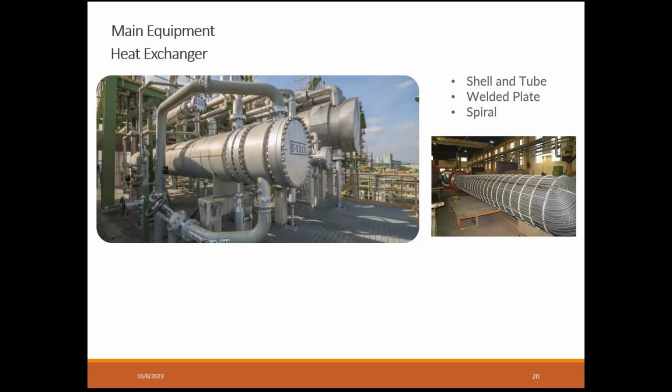So this extra heat is not required. So how do we channel it? Using a heat exchanger. The extra, unwanted heat can be used to heat up the incoming feed. So by preheating the feed, we can reduce the amount of fuel gas consumed by the unit.